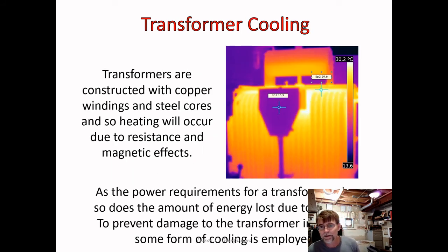So here's a nice picture. Anybody know what this is? This is an infrared shot. It's something that I've done a bit of, in terms of evaluating an electrical installation and determining where or if any maintenance work is required. You will go in with an infrared camera and look for hot spots. Where there is excessive heat being generated, you have the potential for problems, and so you want to address this. What we're looking at here is a transformer.